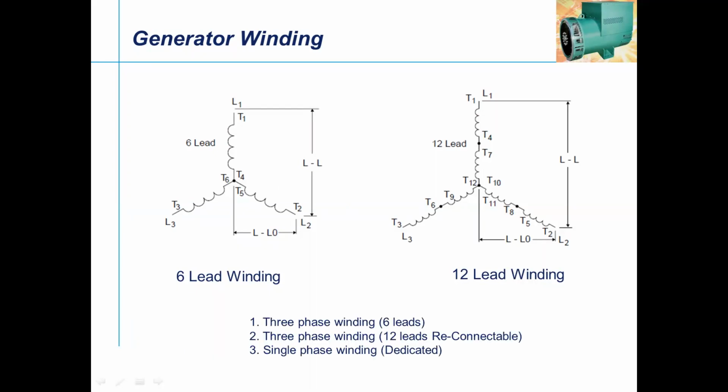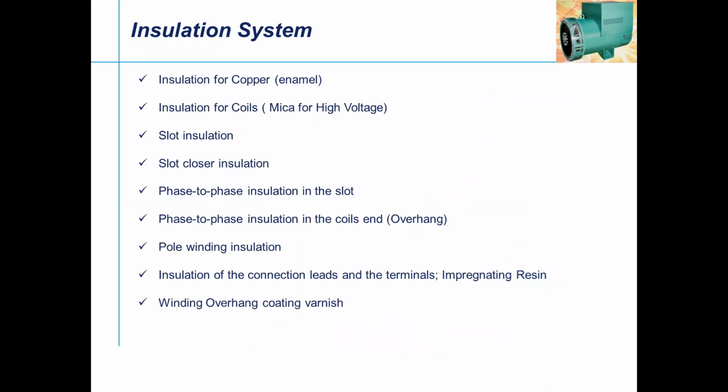And there are 3-phase 6-lead connection and 3-phase 12-lead connection, where you can do a multi-voltage connection, and a single-phase dedicated winding for the telecom application and the commercial household requirements. We have a dedicated single-phase winding.